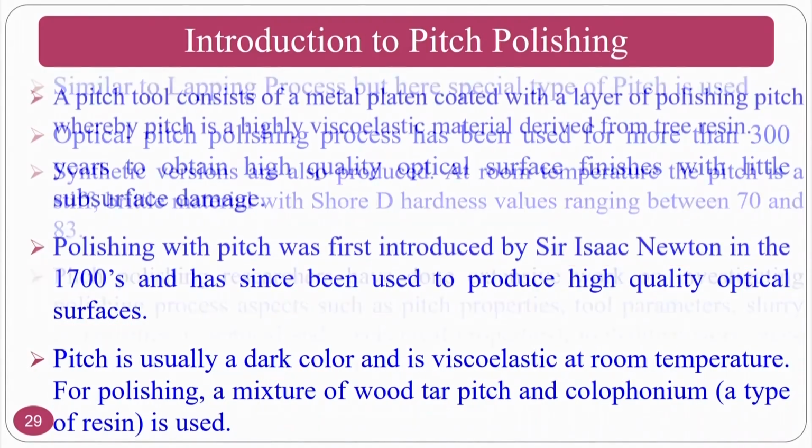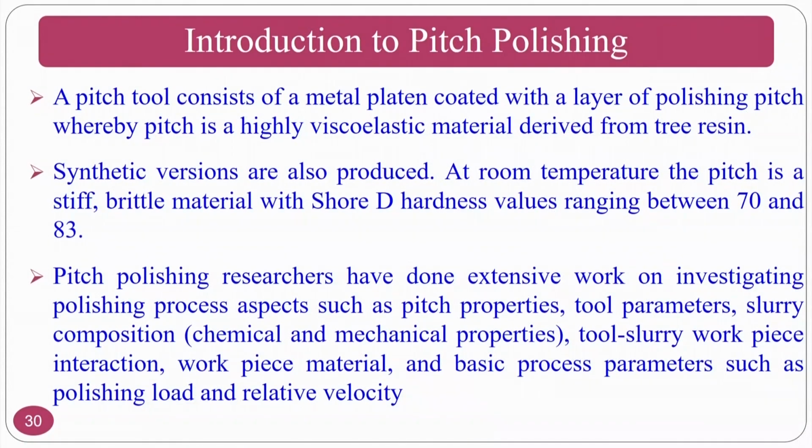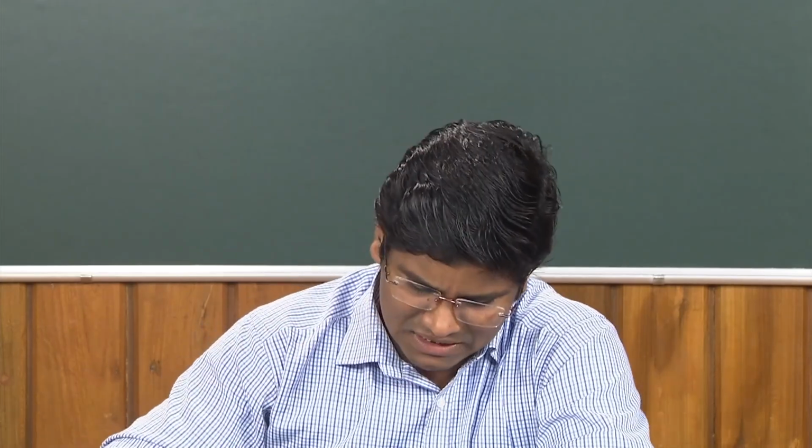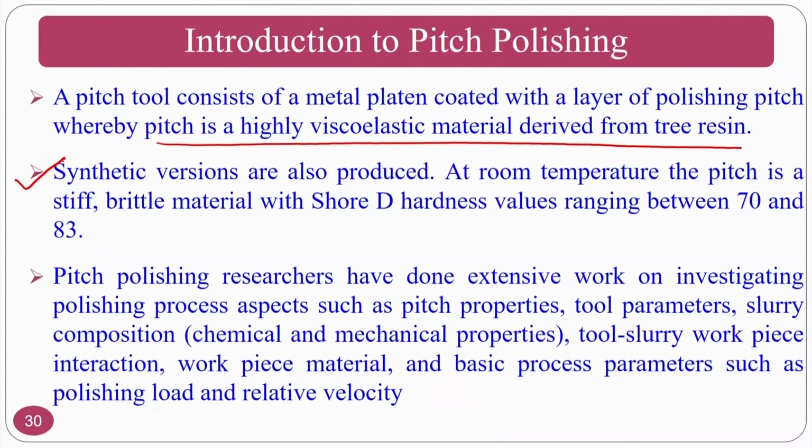and this can be used for optical applications. The pitch tool consists of a metal pattern coated with a layer of polishing pitch, whereby pitch is a highly viscoelastic material derived from the tree's resin. Normally this is a naturally taken material. There are two varieties: one is natural pitches, another is synthetic pitches. Natural pitches are taken from tree resins. Synthetic pitches are also produced at room temperature.